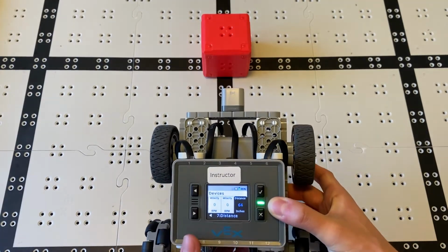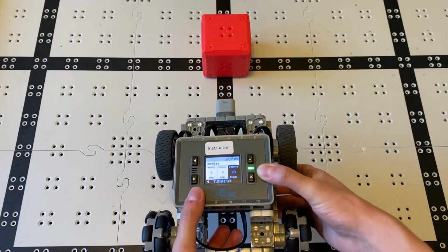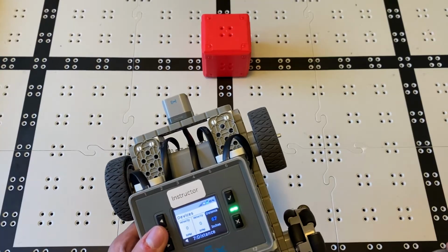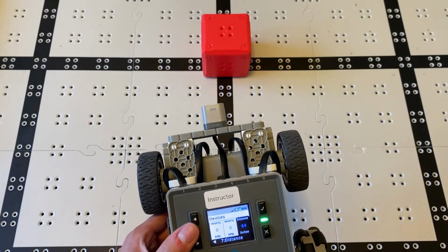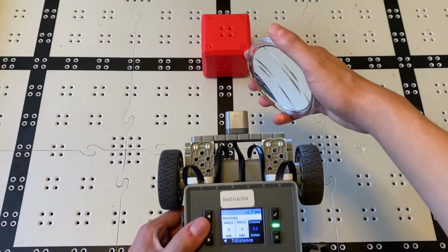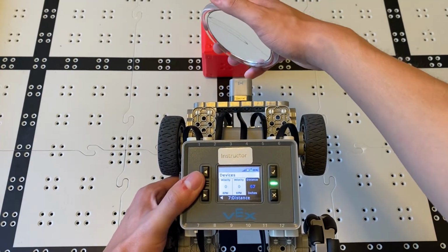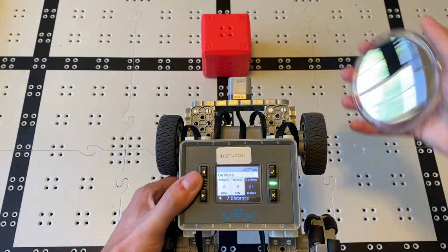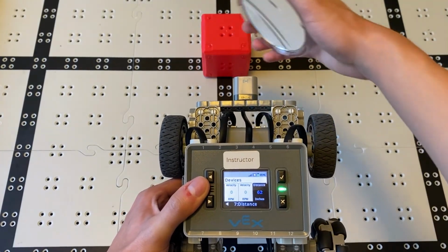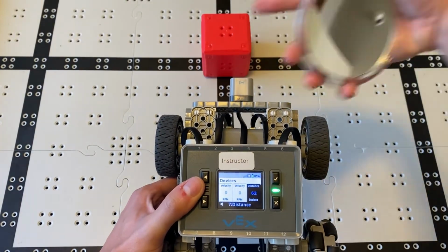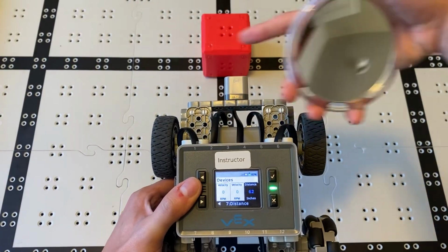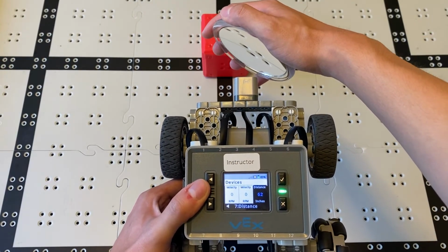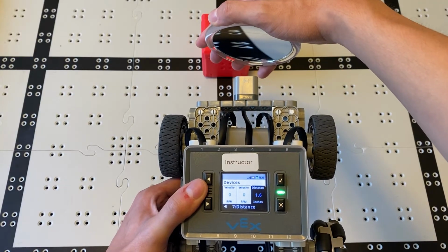Sensor noise might give readings that are slightly too close or too far from the actual value, and the sensor itself has drawbacks as it won't be able to see super reflective surfaces like glass or mirrors. So if I hold this mirror in front of it, it says the distance is 60 inches, even though it's maybe about 3 inches in front of it. The reason why is because it's actually sending that beam of light off somewhere in this direction, and then it's coming back to the mirror and back into the sensor. So it's unable to figure out that the mirror is right in front of it